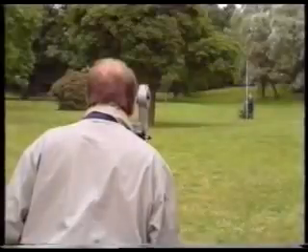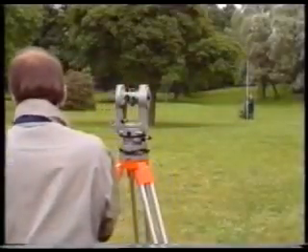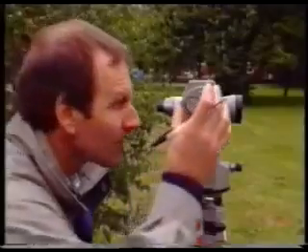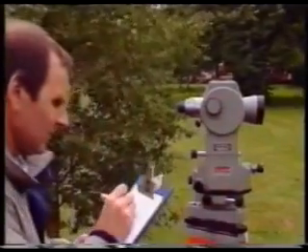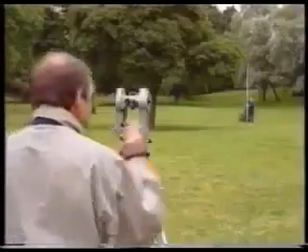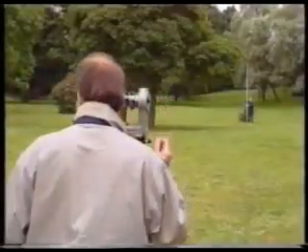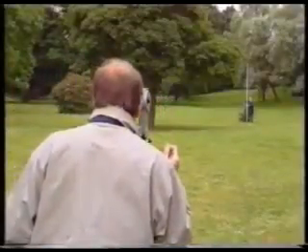As a check, the middle hair reading should be equal to the mean of the stadia hair readings within 1 or 2 millimeters. The horizontal circle is read and booked. The vertical circle is read and booked. And a final check is made on the readings before the staff is signalled to move to the next point